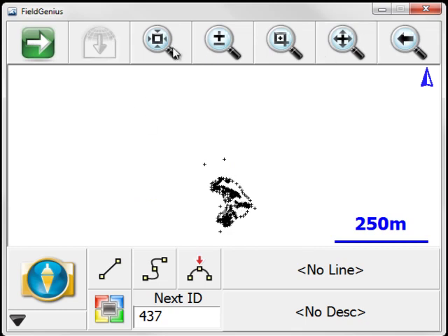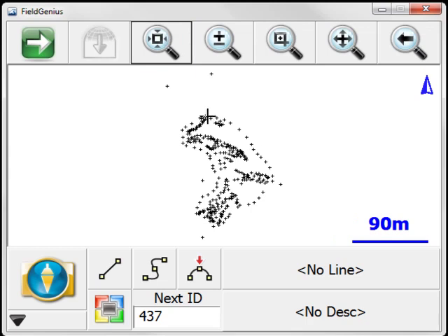And then what we're going to do is create one surface to represent the ground before the stockpile, and it'll be created using just the perimeter B-bank shots. Then we're going to create another surface that consists of all of the bottom shots as well as all the GRD shots in the middle. Then we're going to compare those two surfaces, and that'll be our stockpile volume. At all times we're going to want to have the control points left out of the calculation.